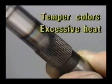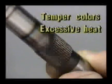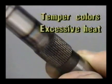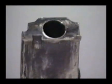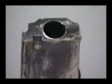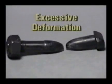Colors such as these mean this part was exposed to temperatures in excess of 500 degrees Fahrenheit. As temperatures increase above 1,000 degrees Fahrenheit, temper colors become black and heavy surface oxides form. Excessive plastic deformation or melting is another good indicator a part has experienced high enough temperatures to lose strength.